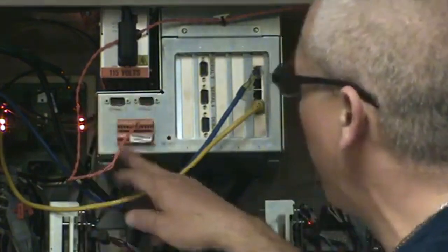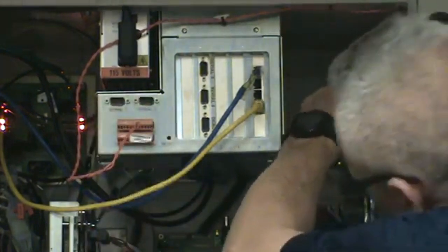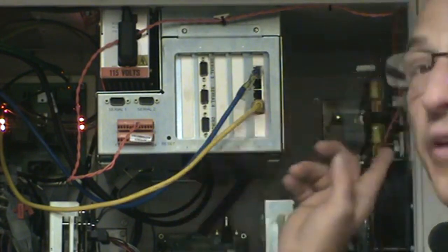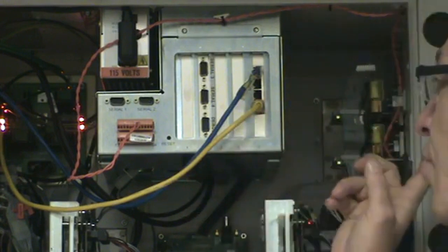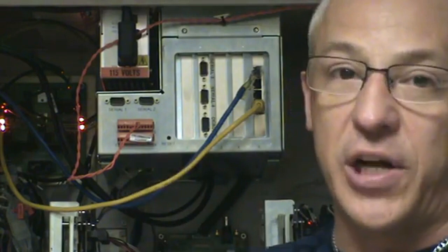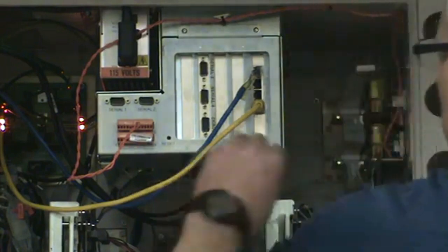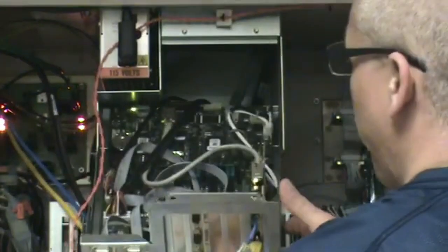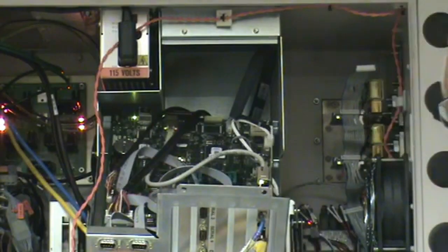That right there is a pressure switch. That pressure switch is coming off over here. If that pressure switch gets low, it'll trip that guy, and then it'll shut everything down on us. So we have to either have enough pressure for that guy to be happy, or you just jump that out, which I did not tell you to jump that out. Okay. Take a lookie. Syscon.